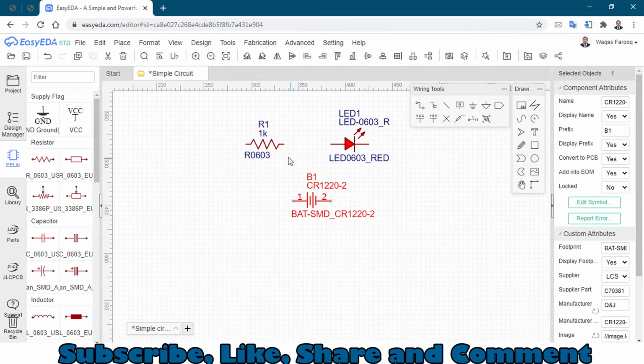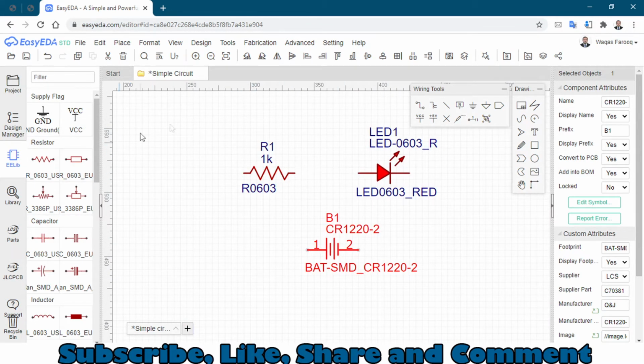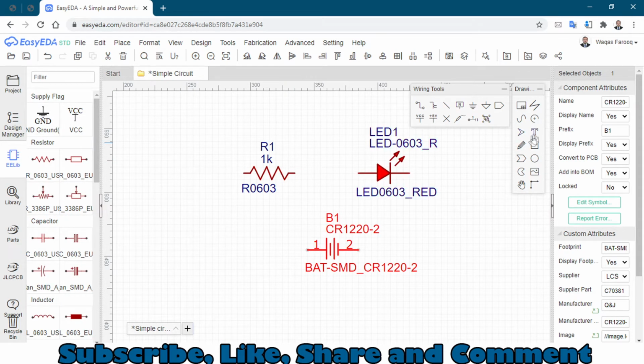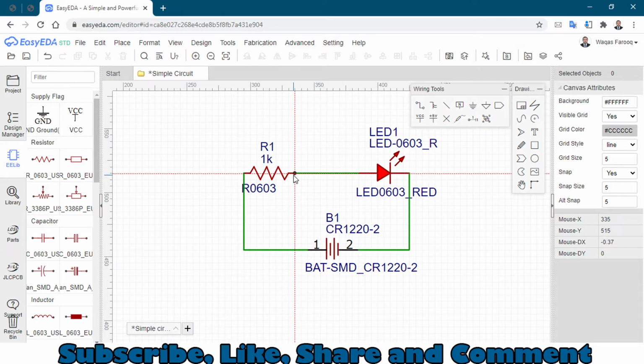Now I'm zooming in by pressing Control and rotating the wheel of the mouse. So let's connect these components. To connect these components, you have to select the wire, and here we have the wire. But if you cannot find the wire, you can click on this bus, or this line, or you can just press W for wire and connect from this to the battery terminal, and from here you can connect to the negative terminal of the LED, and from here to here, and click OK. And you are good to go.